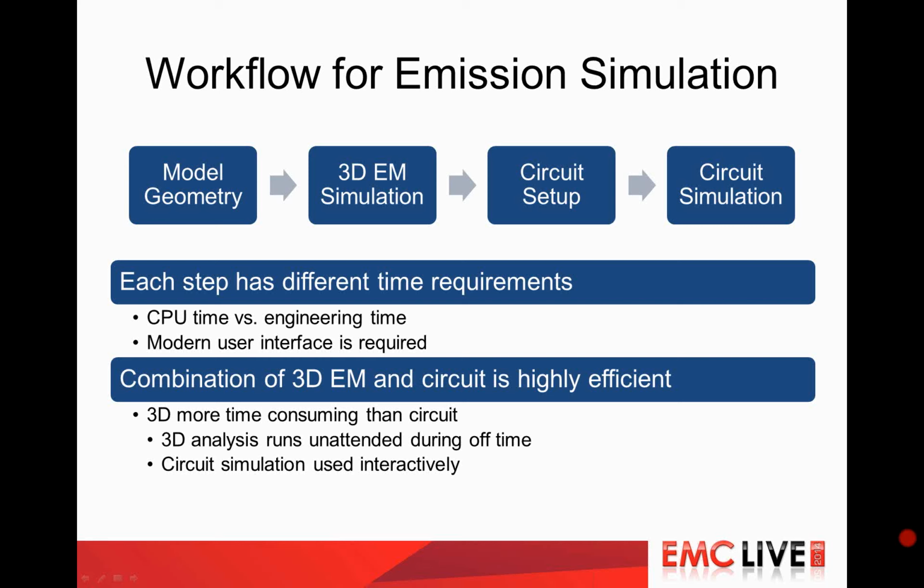So when we look at the time domain method, it is broadband. So if you are looking for broadband results, it's very efficient. However, it needs to run each port sequentially. So if you have many ports that should be excited, the time domain method will take longer. On the other hand, the frequency domain method goes frequency sample by frequency sample. Thus, when you need a broadband result, this will take longer. However, adding a port does not increase the simulation time much.